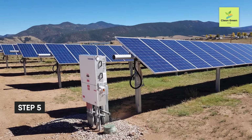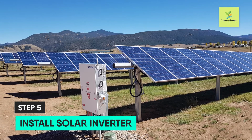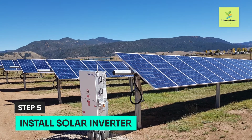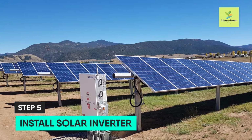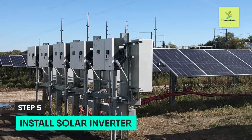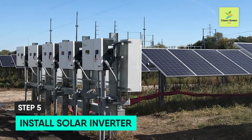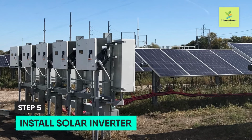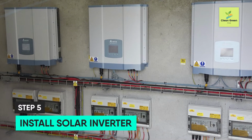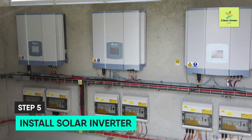The fifth step, installing the solar inverter. After that, the solar inverter must be connected to the system. It is typically installed near the main panel and it could be both indoors and outdoors. Inverters are more efficient if kept in a cooler place. If the inverter is outdoors, it should be kept out from the afternoon sun. If it is indoors, the garage or utility room are usually the best place, since they stay cool for most of the year and have ventilation.